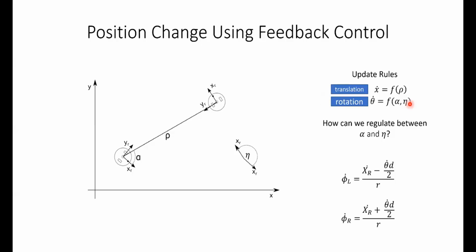But what you do with these functions, subject to the constraint that you're actually keeping in these sources of error, you can multiply it by whatever coefficients you want. So you could say that your theta dot is your bearing error squared, or your bearing error cubed. Probably don't want to square it because then you'll lose your negatives. But some kind of exponential or whatever you want to do, right? As long as you're keeping the absolute sign, because it's just going to affect how important that signal is when you pass it into these inverse kinematics equations.